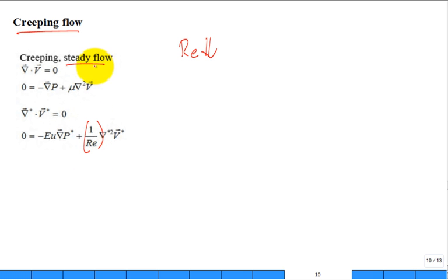If it's steady flow, then that whole transient term goes to 0. And so you would just have some sort of pressure around it, and you'd have this viscous term surviving in the Navier-Stokes. So you have the general equations, and you say, for this type of flow, these terms drop out. For this type of flow, these other terms drop out. And then you can solve it.